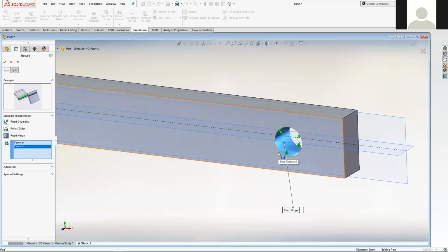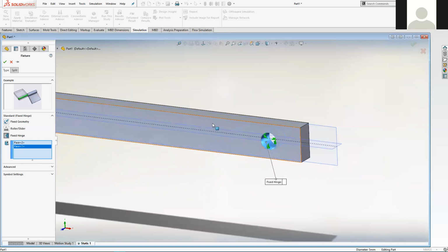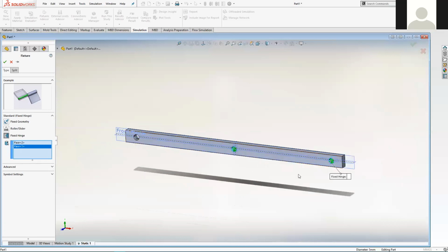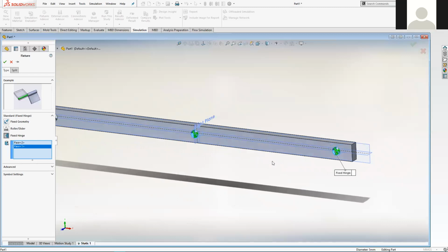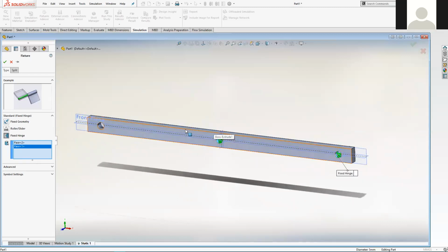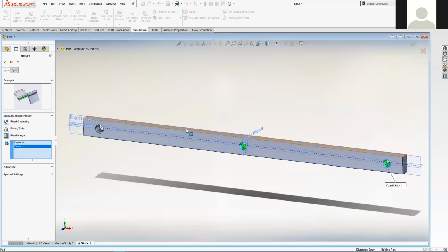That allows no rotation, no movement of any kind, which we talked a little bit about last session, is somewhat unrealistic. If you're trying to simulate something as close to real world conditions as possible, the fixed constraint is a bit of a blunt tool. It loses some subtlety that you get in the actual real world setup. So yeah, fixed hinge on both of these.